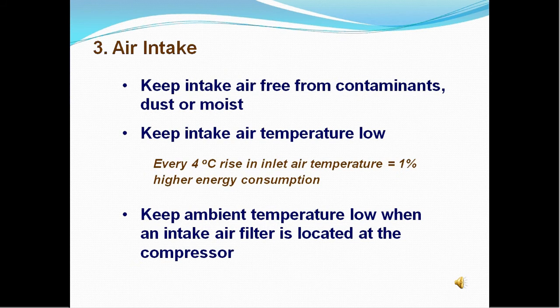The effect of intake air on compressor performance should not be underestimated. Intake air that is contaminated or hot can impair compressor performance and result in excess energy and maintenance costs. If moisture, dust, or other contaminants are present in the intake air, these contaminants can build up on the internal components of the compressor. The compressor generates heat due to its continuous operation. This heat gets dissipated to the compressor chamber and leads to hot air intake. This results in lower volumetric efficiency and higher power consumption.